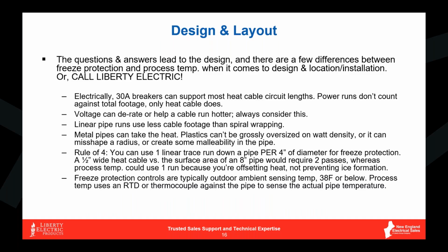We talk about linear pipe runs versus spiral wrapping. I know that a lot of pictures online that you might look at show spiral wrapping. Well, the math to do a spiral wrap around a pipe is take your pipe diameter times 3.14. And when you start seeing how much more cable that's going to cost you to spiral wrap around that pipe, I'm sure you're going to want to change to linear pretty quickly, because it's going to be less than half of what you're going to pay to spiral wrap that pipe.